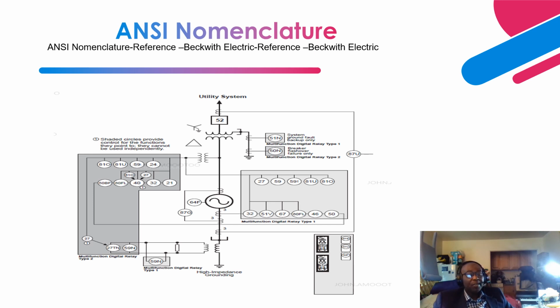Next is directional reverse power flow. Let's say you have a reversal of power flow into the generator from the AC grid. Then this generator is going to convert from a generator to a motor, and you don't want that. It's going to cause heating and a failure of the generator. So this relay detects that reversal of power flow from the AC grid.